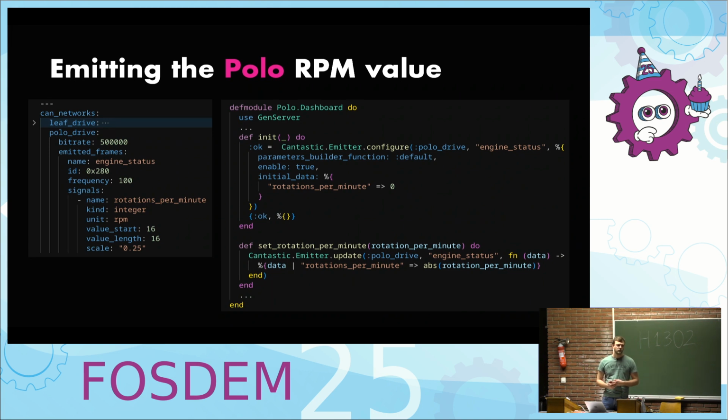So do you mean that the CAN bus lines from the OBD connector are different from the others? So there's a proxy or something in between? Yeah, there is in most cases, so it depends. Like in the Leaf, they expose in the OBD two lines, one for the internal bus and also one for the standard one. But on the VW, you just have a filtered version of the CAN.